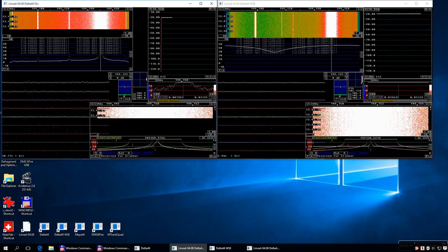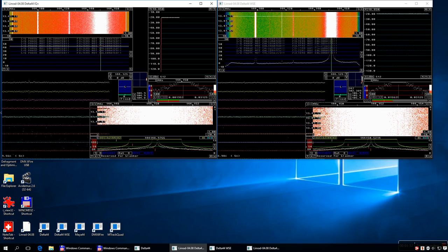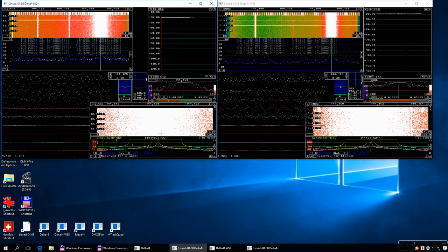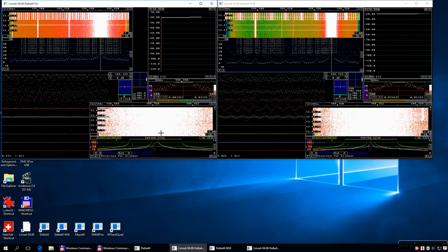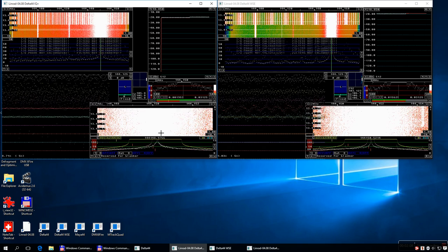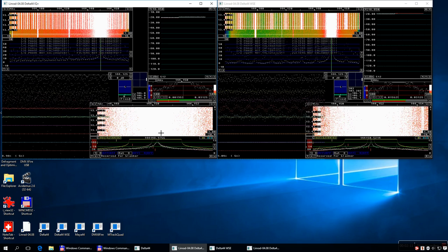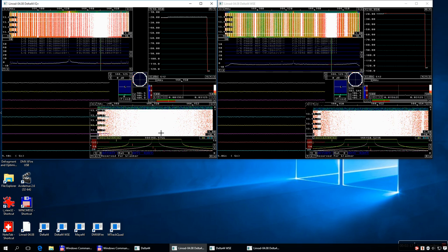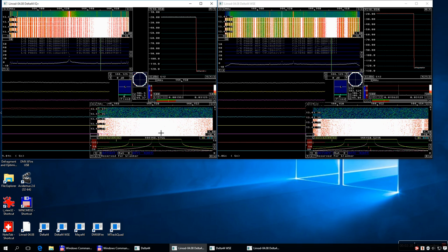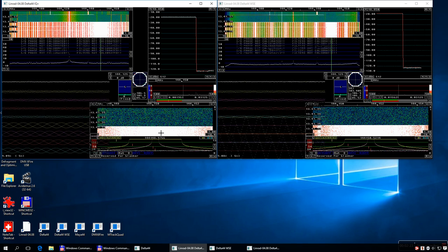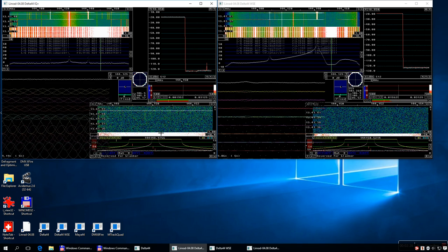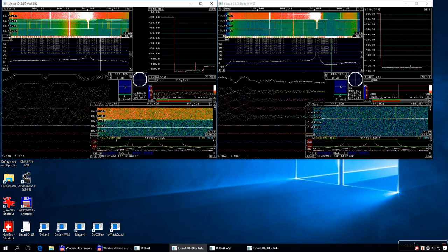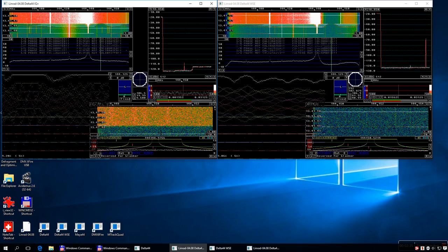And you can see both indicate minus 20 dBm. I increased the level by 1 dB, and then both receivers saturate. So they have the same dynamic range if you just look at the noise floor and the single strong signal. I can now put a signal 10 kilohertz away in frequency, this one, and make it strong. Like that.